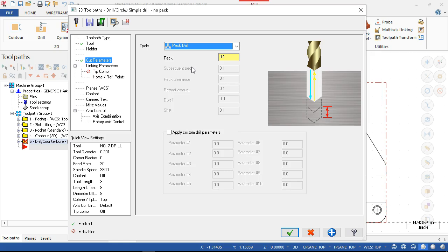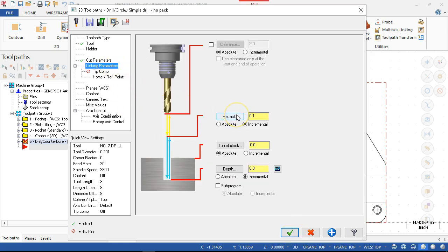Then we start looking at the tool life, longevity of, we ran 200 parts. It's time to change that tool out because our go, no-go, just no-go. Or just go or whatever. The reamer's oversizing the hole. Yeah. Undersizing. Yeah, it would be, as it wears, it'd be undersized, yeah.